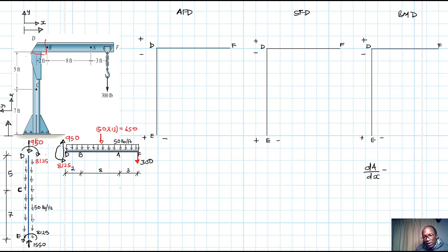All right, this is going to be equal to q, and therefore axial force itself is just the area under the distributed loading diagram, which is the axial force in our case. This axial force is distributed along the column, and then the change of shear with respect to x is also equal to the distributed load, and shear itself is just the area under the loading diagram perpendicular to the beam.